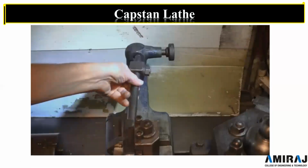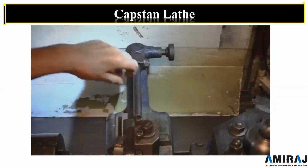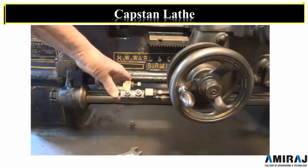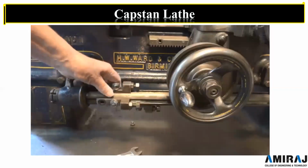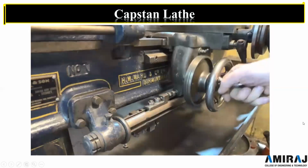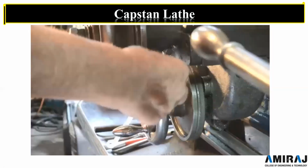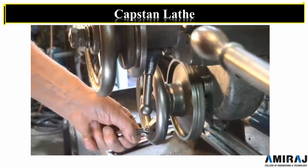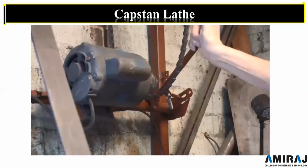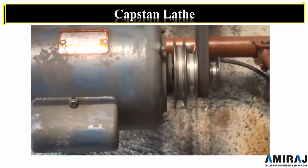A stop can be fitted to the cross slide to control the finished diameter of a part, although I rarely use it. The saddle has multiple stops that can be set to limit the travel, very useful when turning or boring to a prescribed depth. When parting off or facing material, the saddle can be locked in any position along the bed. To engage or disengage the drive, the motor is simply raised or lowered.